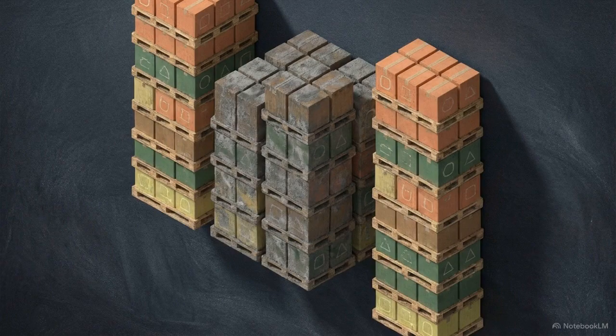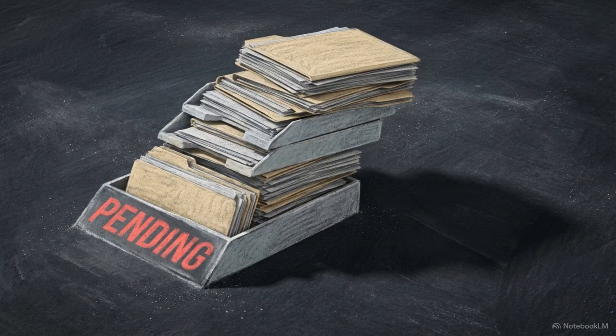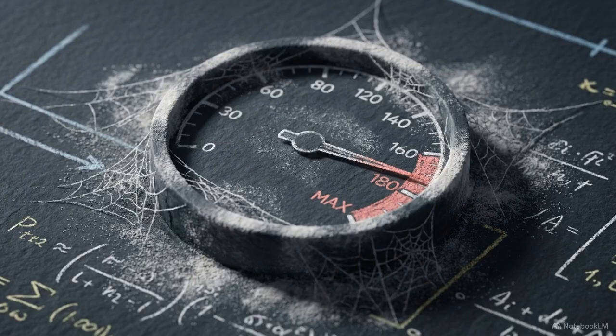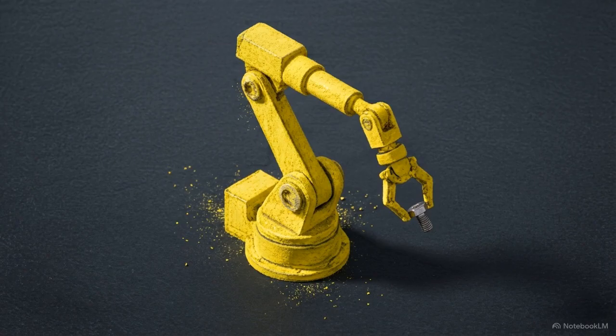Because these idle queues dictate the timeline, lead times are rarely deterministic. They are highly variable and frequently much longer than anticipated. This queue-heavy structure reveals a hard truth about industrial engineering. Lead time is strongly influenced by the overall process design, not the speed of individual machines. Upgrading to high-speed robotic assembly arms rarely improves delivery dates for this reason.